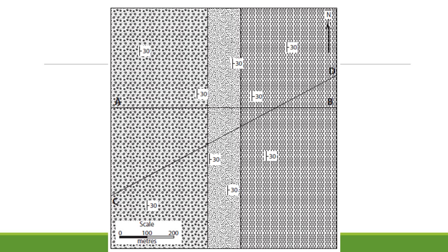Alright, now moving on to exercise 3. This one was just a little bit trickier than the other ones because you now have some dipping geology. So we've got our strike and dip symbols on here. It's striking in this direction. Remember, the long line indicates the direction of strike, and it's dipping in this case towards the east because that's what this little tick means.